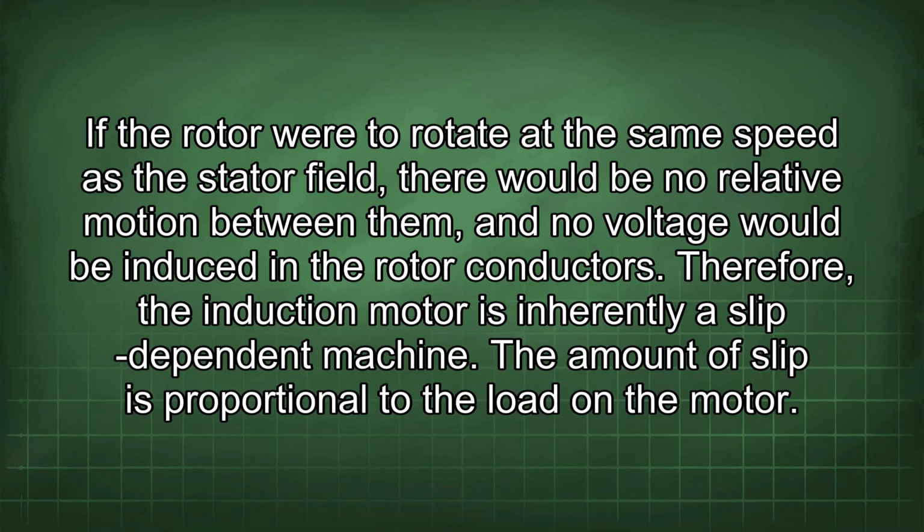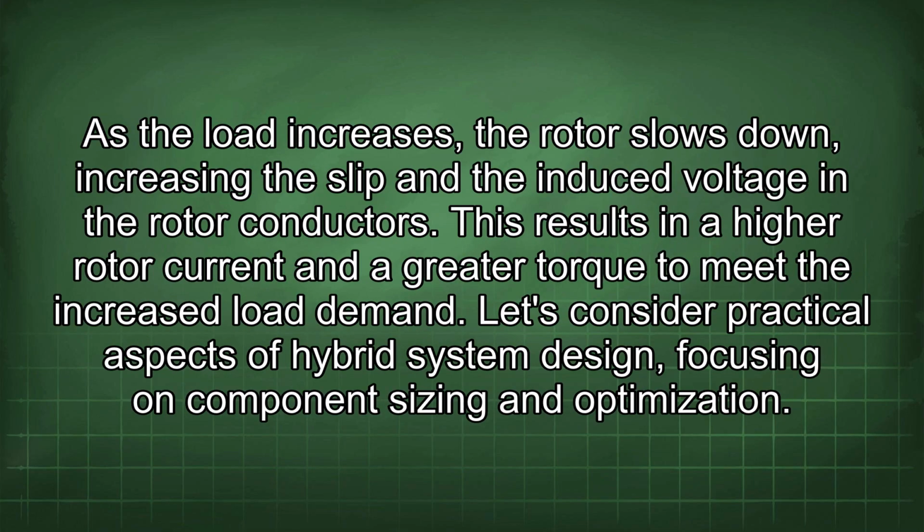The amount of slip is proportional to the load on the motor. As the load increases, the rotor slows down, increasing the slip and the induced voltage in the rotor conductors.